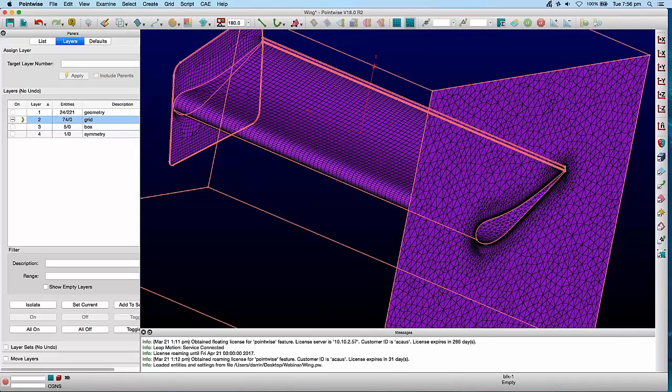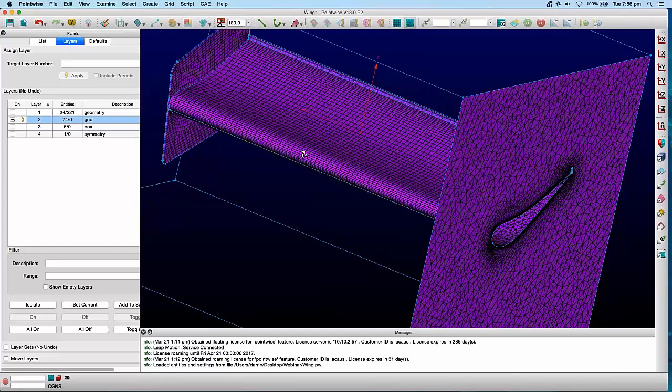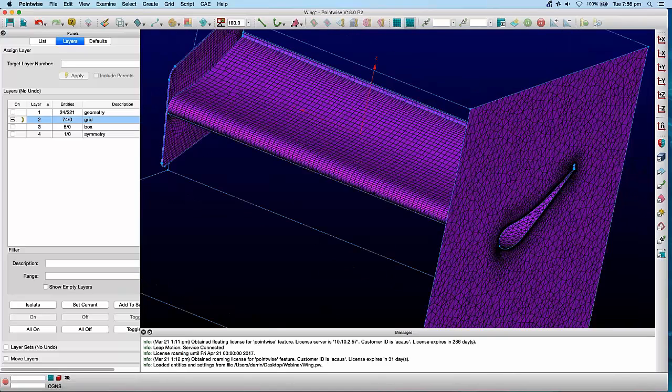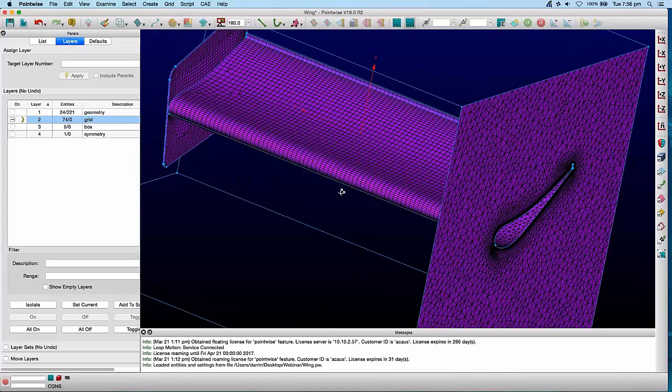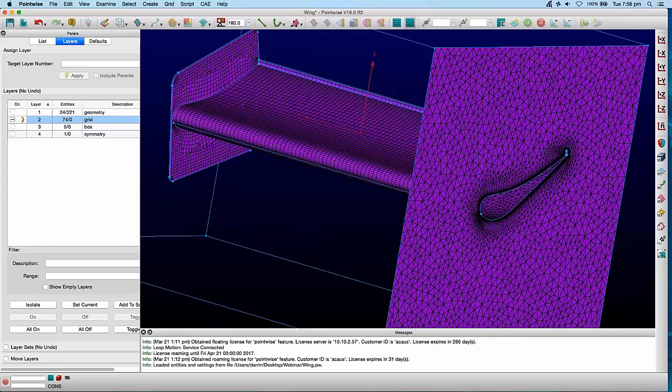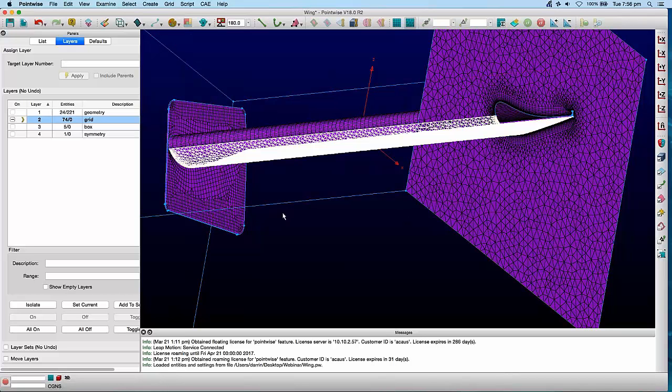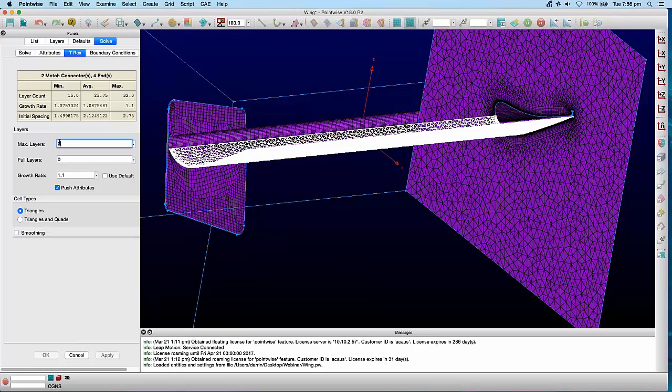If you're an advanced meshing person or a CFD person that's been doing meshing for a very long time, you'd probably say to me, hey Darren, that's actually a rectangular surface, we could have just done a structured mesh on that. And the answer is, yes you could, but in this case there's a couple of clicks and I've got it without having to think too hard about it. And I can do the same for the bottom, and I'll do that here.